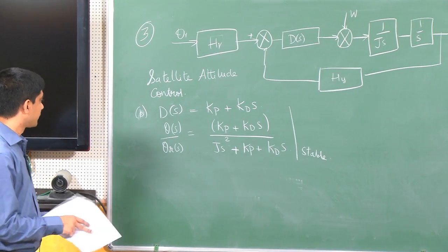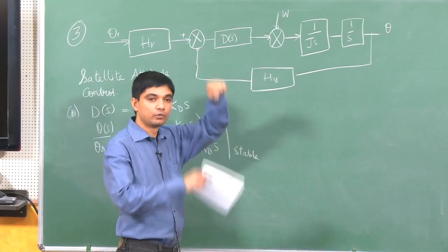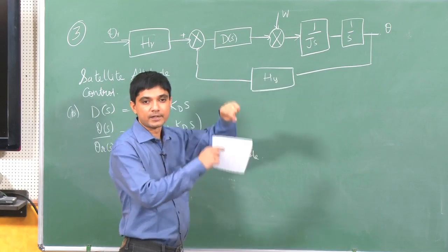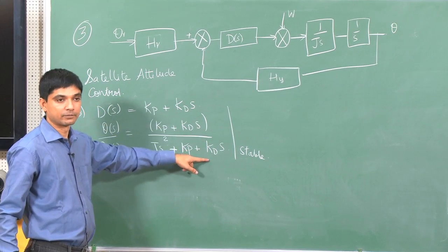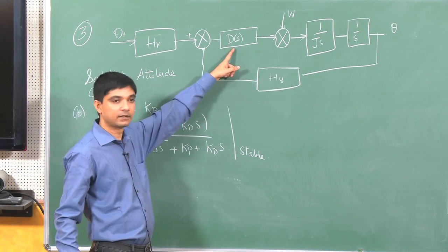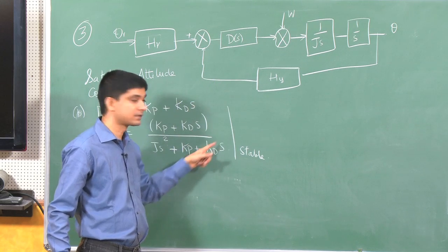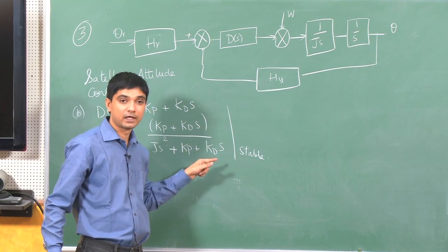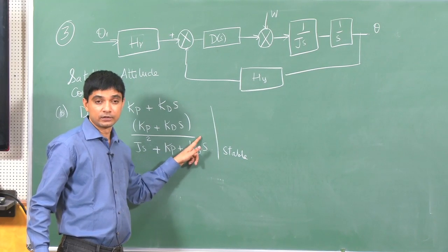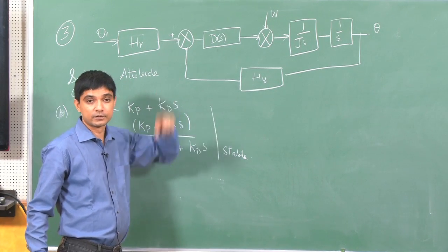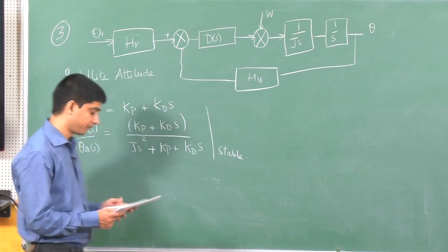Okay. So, first thing, with a proportional controller I could not stabilize the system, I could just move the roots of the system along the imaginary axis. I put a derivative term, I add damping to the system, right. In the first case we just had ds being a proportional controller, I did not have this damping term. This term corresponds to 2 zeta omega n, which means zeta equal to 0 if Kd is equal to 0. There is no damping, so the system will always be oscillatory. In the second case, I introduce a damping and stabilize the system.